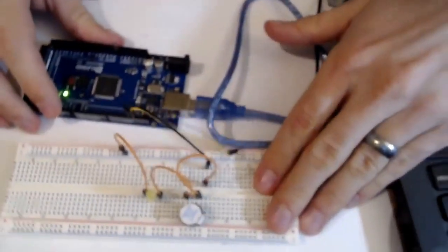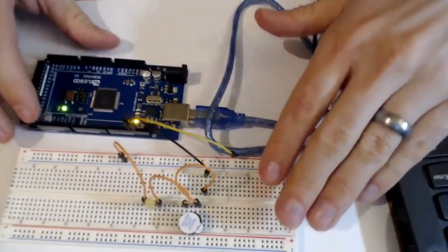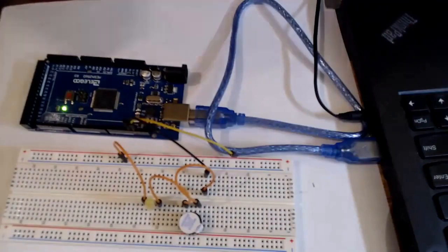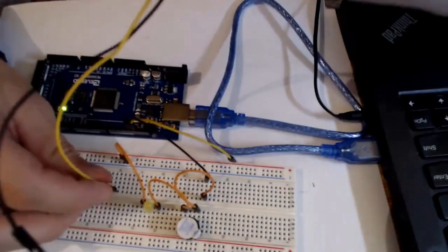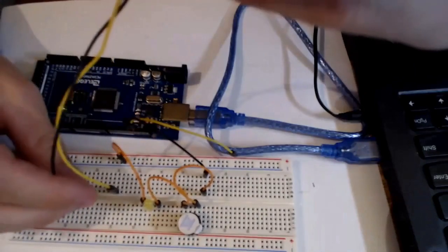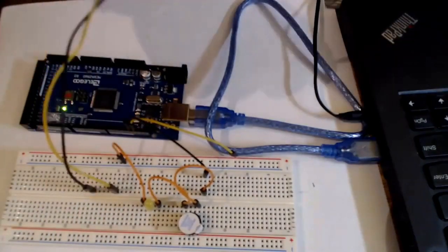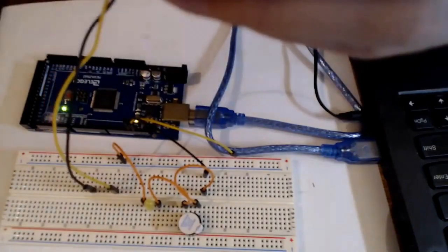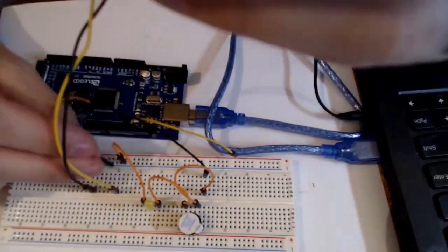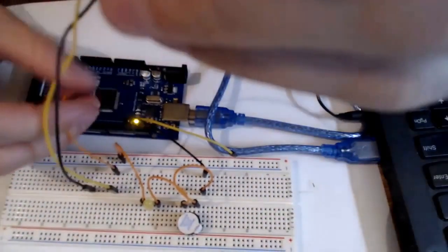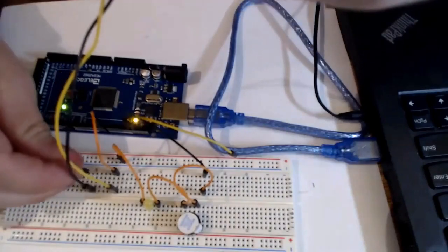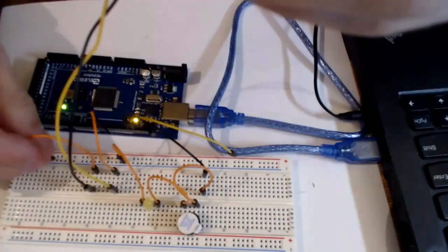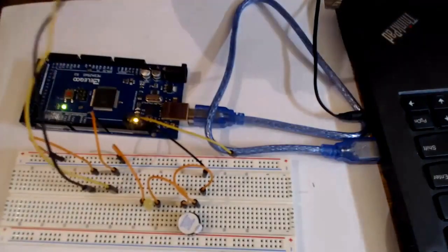Okay, so here's my breadboard. I'm going to take one lead of the tilt switch and put it over in, I think it was 40 on the diagram, I kind of forgot. So I'll go with 40 and 45. So off in the middle of nowhere right now. One side, I'll say column 40, is going to go to pin 7. And to complete the circuit to ground, I'm going to bring column 45 over to the ground rail. So that's the whole circuit.